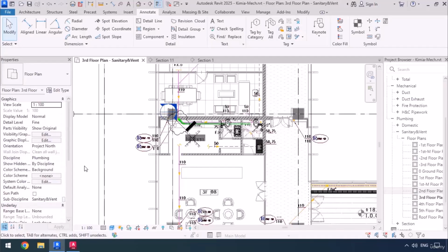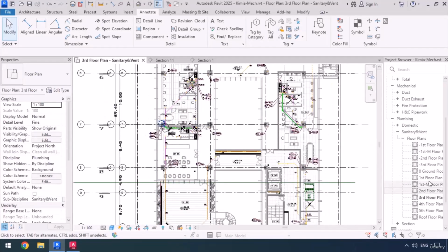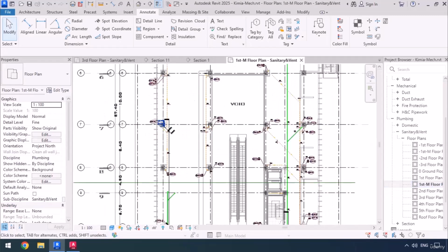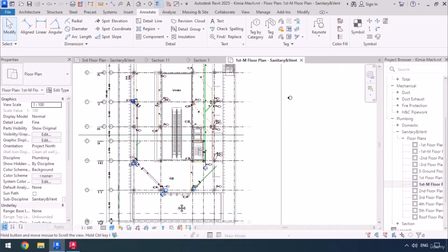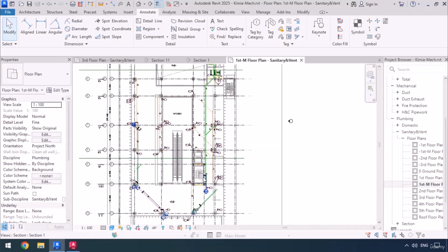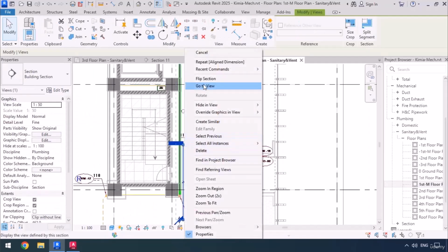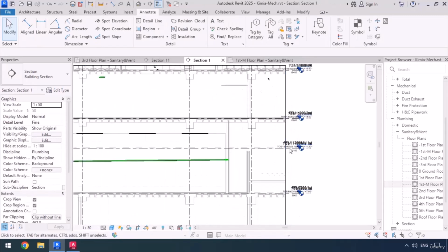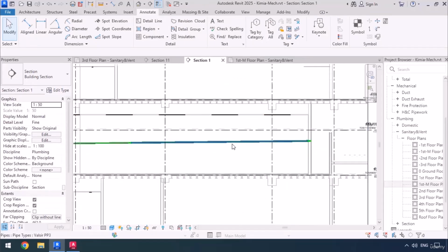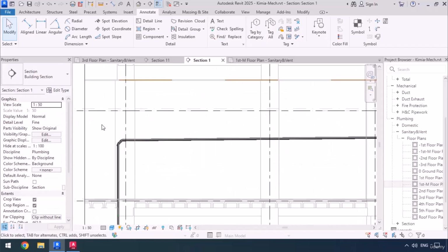Now to check all of the risers that we have placed and drawn, we're going to once again check the mid-1st floor. And you see here we have a pipe which we've rectified its elevation, and I feel like we're going to need to check it again. So I'm just going to go into this section, right click, go to View, and you see this pipe can't be placed over here in the mid-1st floor, and it needs to be below the ceiling of the 1st.